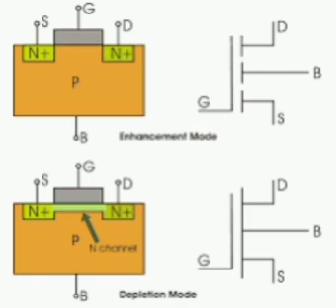In a Schottky diode, the reverse current is due to majority carriers that overcome the barrier, hence weak temperature dependence. In a PN diode, the forward current is due to minority carrier injection; in a Schottky diode, it is due to majority carrier injection. In a PN diode, switching speed is controlled by recombination of minority injected carriers. In a Schottky diode, switching speed is controlled by thermalization of hot injected electrons across the barrier.